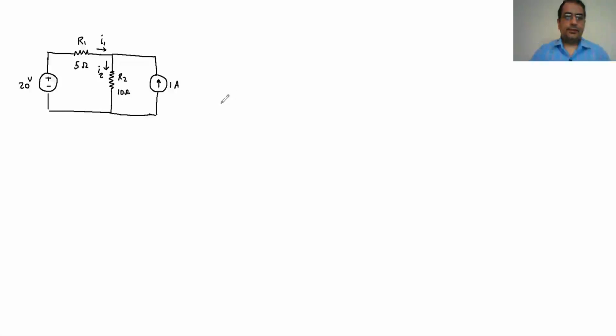So look at here. I can do this in two ways. Here I have a battery in series with the resistance. Also, I have the current source in parallel with the resistance. So I either can take these two and replace it with, so these two are like the Thevenin, and I can replace it with the Norton.